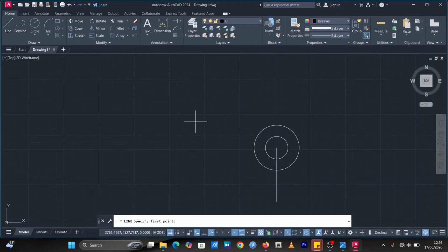You pick your line tool, you click here at the intersection point, you move to the left, you input your 76, and then you press enter. Now the circle has a radius of 20. So whilst holding your line tool, you move up, make sure your line is straight, and you input 20, then you press enter. After that, you can press escape.